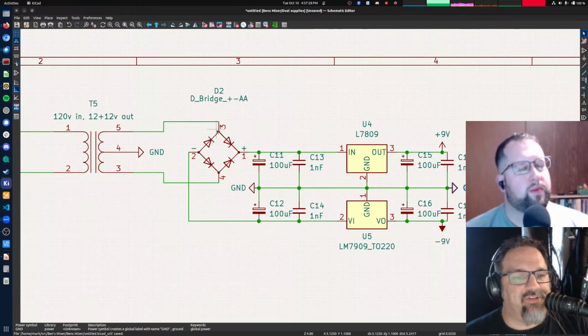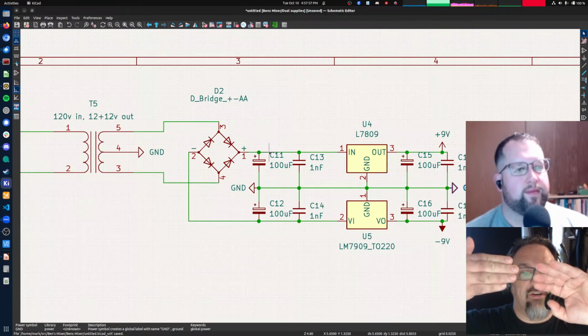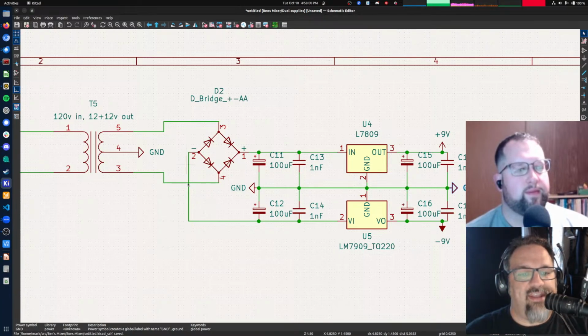We take that positive voltage coming in here, and it'll pass through that diode over here to this positive side, and this is a negative voltage over here. It'll take that negative voltage, go through that diode out to the negative side. And then these alternate, and now this is negative and this is positive. So this negative voltage will pass through that diode and create a negative here, and this positive will come in through here and go through that diode and create a positive here, right? So all the positive halves of these AC signals are coming out through this wire, and all the negative halves of these AC signals are coming out through this wire. Does that make sense?